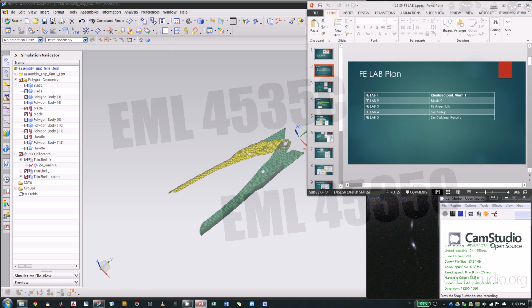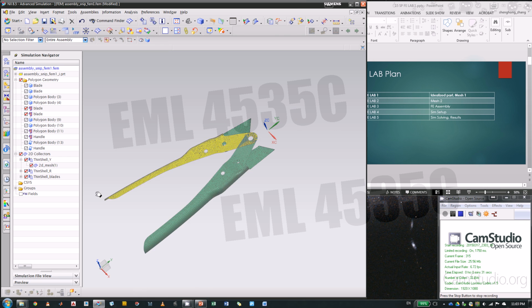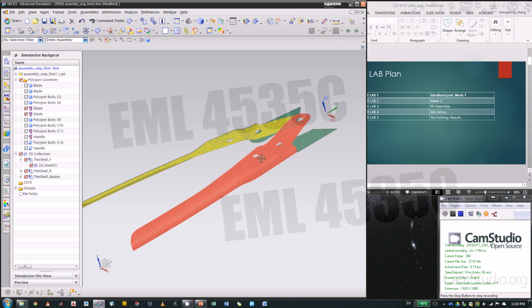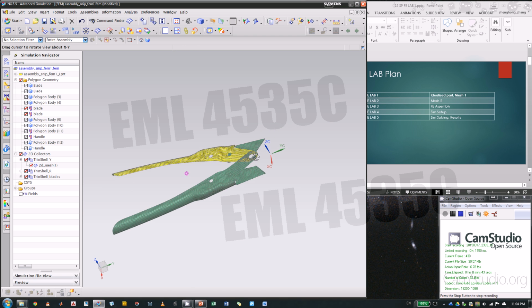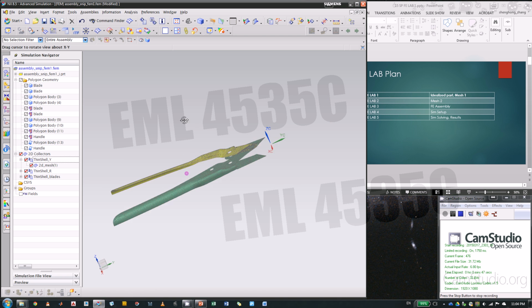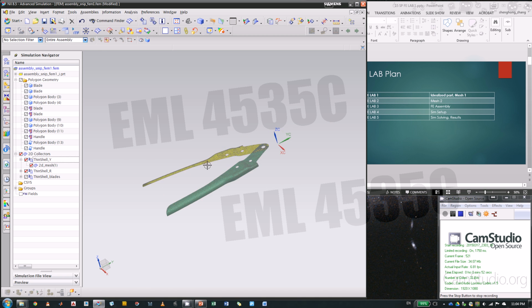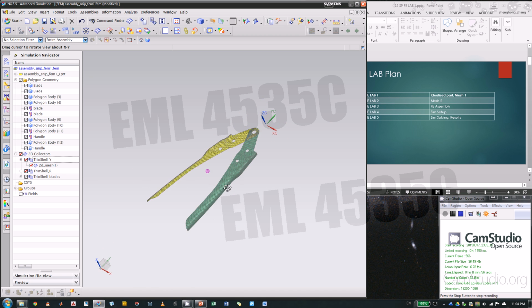Okay, so the FEM2 lab is mesh. In this lab, we will generate the whole mesh for the handles and the mesh for the blades. First, for the 2D shell, we can hide the polygons. We don't need to deal with them. Then we can hide the shell on the blade. So we have these two pieces of handle, half.